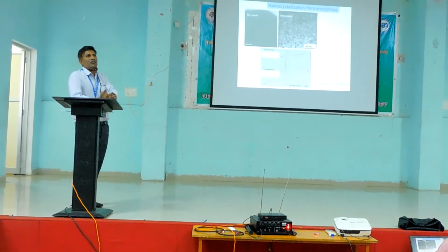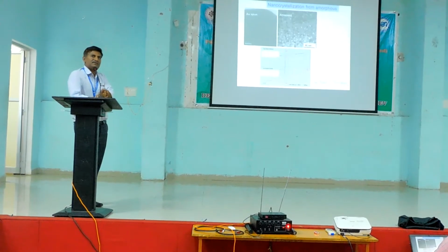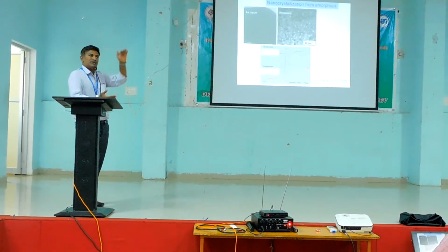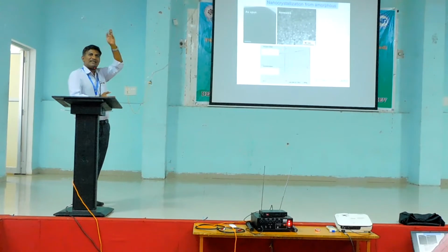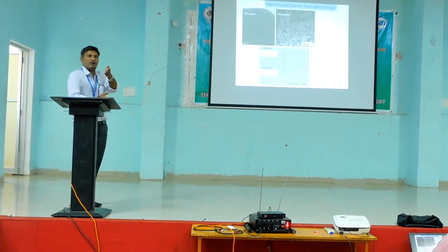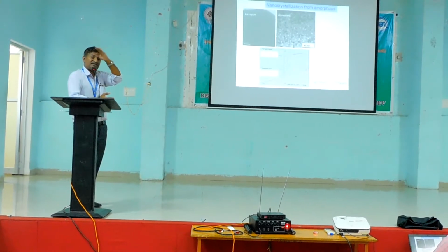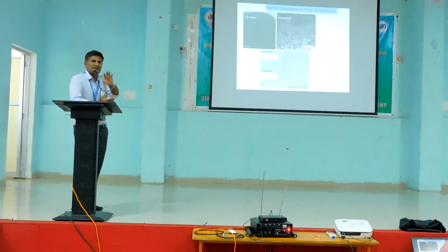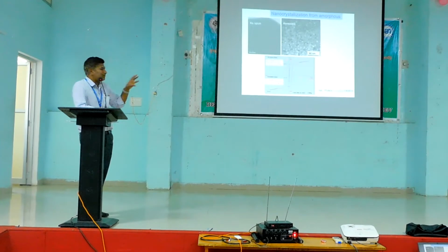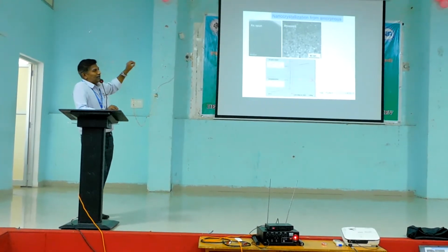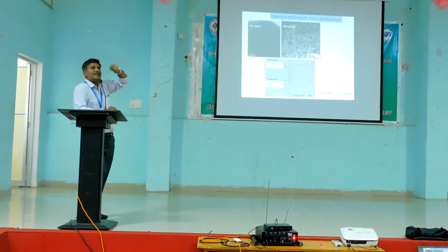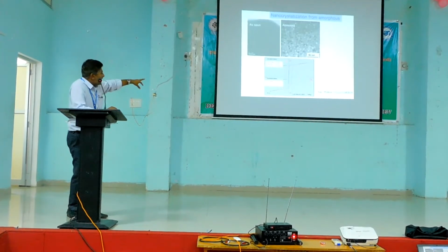See, what does the inverse Hall-Petch relationship say? The strength will keep increasing as your grain size is coming down. Okay, but again after some time there is a change. That's what the inverse Hall-Petch relationship is. Similar to that, when the nanomaterial is around 20 nanometers, in that range, again you will have very low losses.